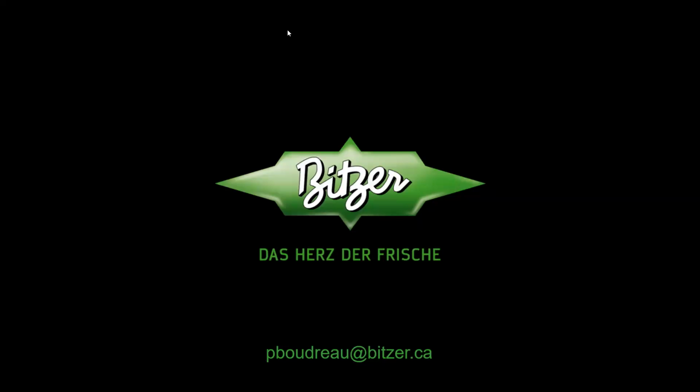Thank you so much. A few more questions for you. What is the difference between liquid flooding and liquid slugging? Liquid flooding is basically liquid draining down the suction line and entering the compressor. And then, that liquid can then enter your lubrication system and create problems with it directly. Slugging is when that liquid actually enters the cylinders and then the piston tries to compress that in the cylinder. Okay, so that would be liquid slugging. And liquid slugging, as I said before, can result in damaged valve plates and or blown gaskets on the valve plate.